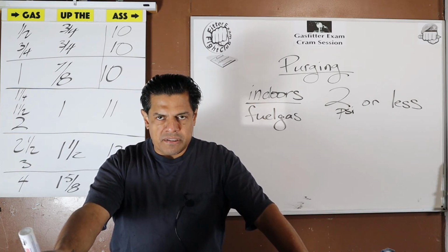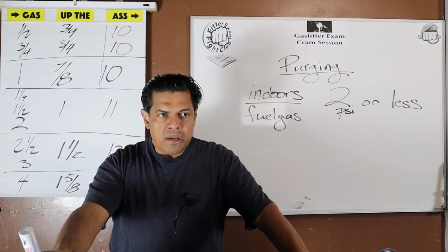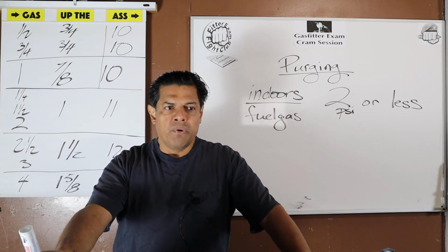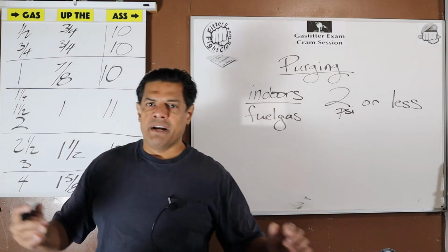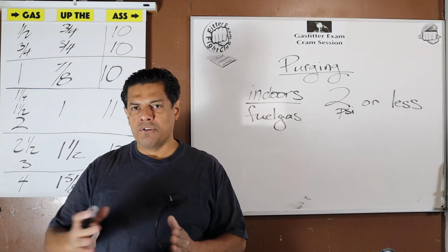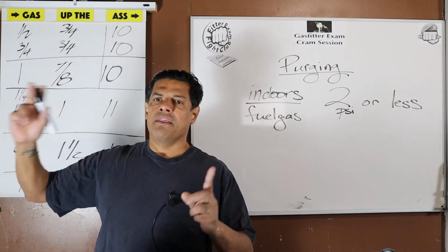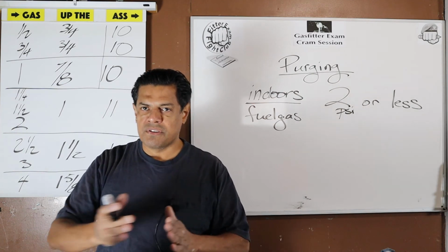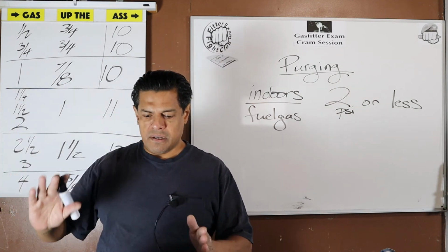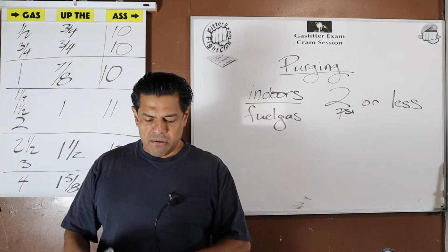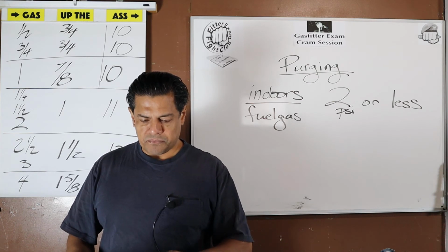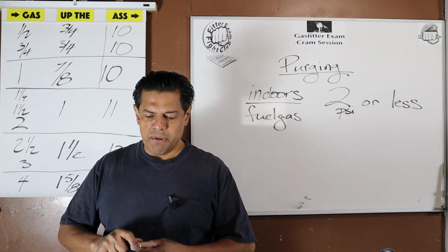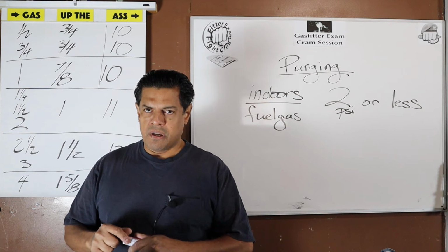Depending on the kind of system you're working with, when you're turning on, you might have to first purge with inert gas. Then you can send the fuel gas in. But for now, we're going to stick with this question. Piping systems may be purged indoors.